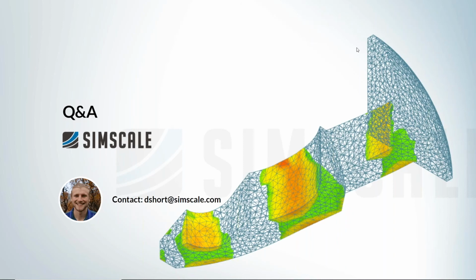I would say that the forces are not changing quickly enough for a dynamic analysis. In a dynamic analysis, we would be expecting inertial effects to come into play, and for me that's over about 10 meters per second in terms of an impact velocity. Below that, if we're not thinking in G's and actual dynamic shocks, then I don't think this is sufficient for coming into the dynamic domain, in my opinion.